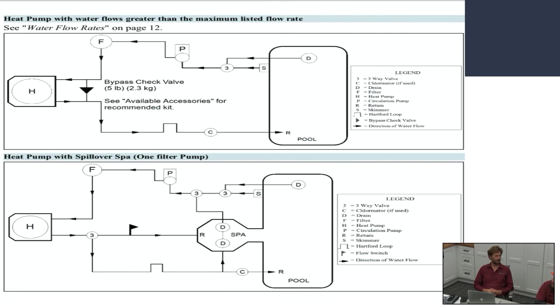High head pressure. Yep. Or if it's a gas heater, high limit. Yep. That's exactly right. So we have our high limits, which work as the safeties instead of the high pressure switch on our heat pump. Running the gas heater, it's the high limits, which is water temperature. The water temperature gets really high, the high limit switch will open. And if it opens too many times, it'll pull a lockout. But it's designed so that when it cools back down, it'll close on its own. But they will sometimes fail open. If they've been triggered to open a lot, they will fail open.